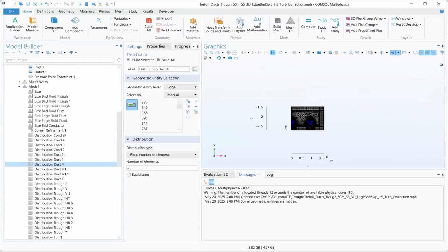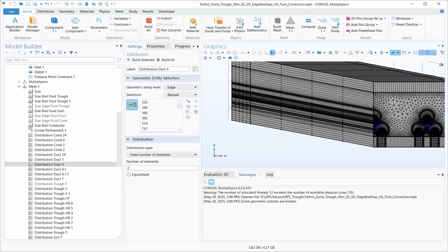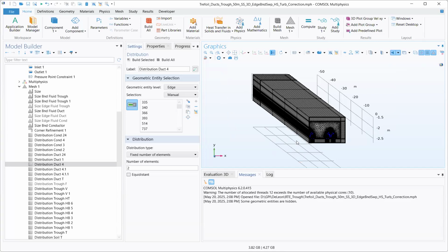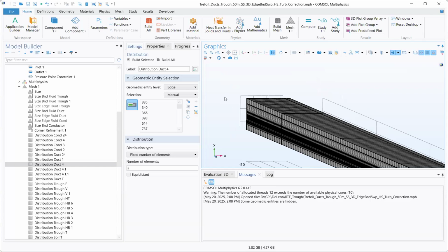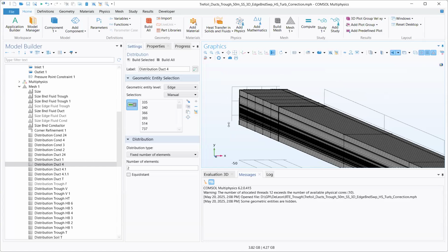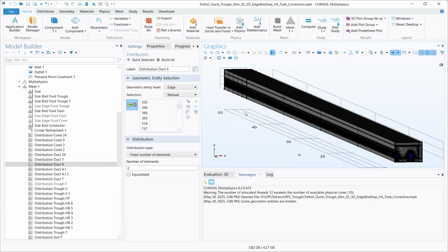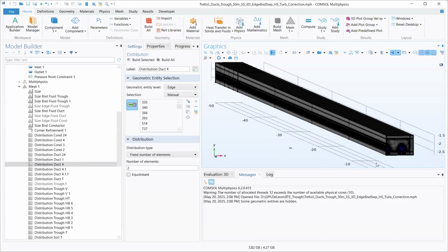Let me show you the mesh. So it's not only mesh like a face, right? Like 2D. Now we need to mesh along the axis of the fluid flow, right? So we need to first, very important, mesh the fully developed region by a few slices. And then after, where the fluid flow is changing less, we don't need to have as many slices in between. Really, what I should have done is I should have also sliced at the end of the tunnel.